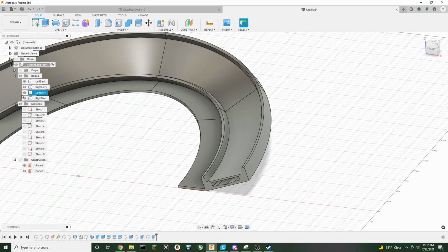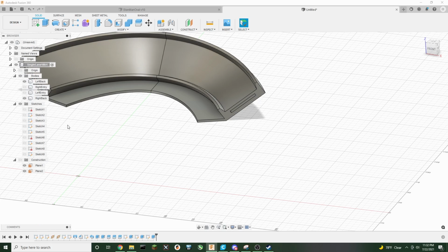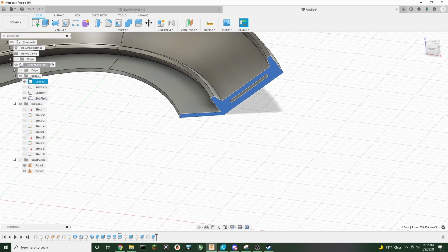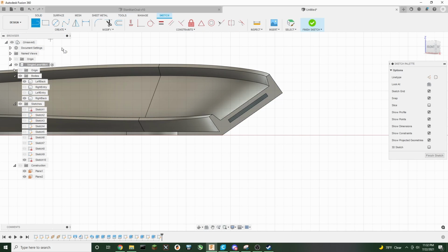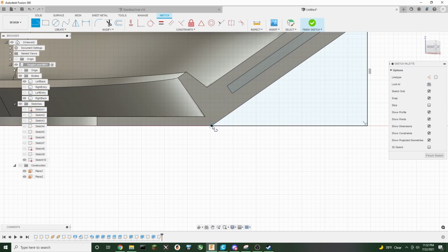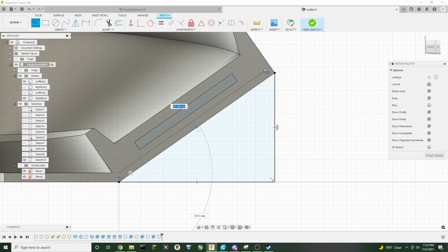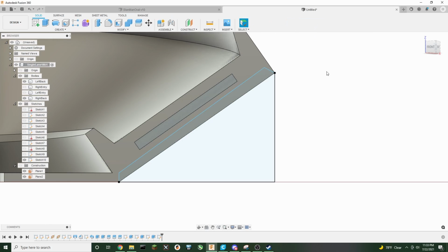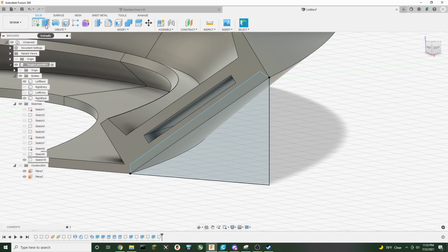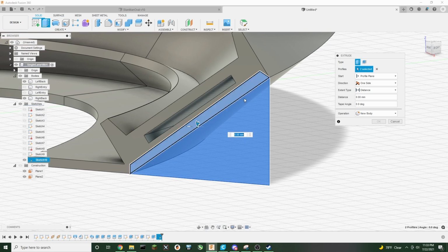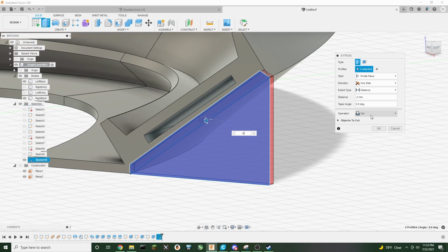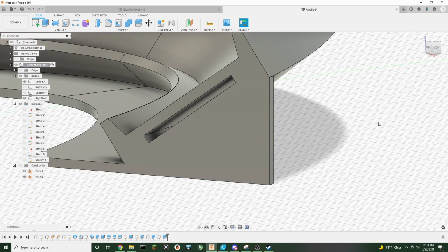So we're going to hide the 2 entry pieces. I'm going to do this one first. I'm going to sketch on it. We're going to go from here down, then over to this. And then so we don't get in trouble, we're going to go from here to here, to here, to here. Finish that sketch. We're going to extrude this guy -2. It's going to join. Say okay.